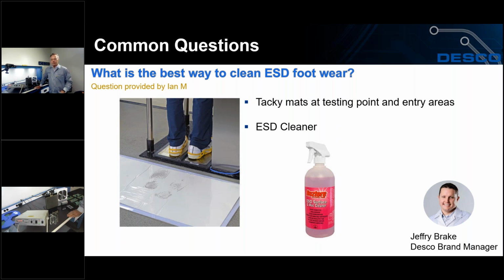If they get extremely dirty, or if you feel like you need to clean them a little bit more, use something like an ESD cleaner, like the ESD Restore cleaner that Desco provides. You can take the foot grounders off, scrub them down, and clean them up real good. ESD Restore doesn't leave behind any insulative residues, so a cleaner like that is going to be better than normal household cleaners. So that's the best way to clean them if you feel like your foot grounders are getting dirty, or that's what's causing you to fail your daily testing.